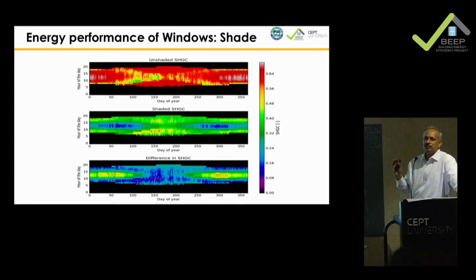From Chennai to Simla, east and west, go for vertical with a little bit of angle. Southern side, go for horizontal. Right? So this is how all your high-tech low-E glass can be combated with simple construction, provided you are open to accept the aesthetics given by shading devices. And you have various kinds of shading devices you can have.